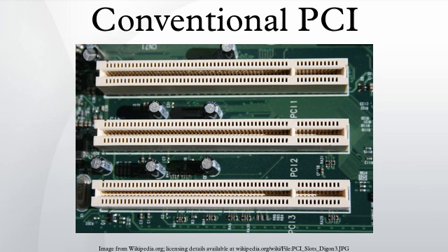If a memory space is marked as prefetchable, then the target device must ignore the byte select signals on a memory read and always return 32 valid bits. 0111, memory write, this operates similarly to a memory read. The byte select signals are more important in a write, as unselected bytes must not be written to memory. Generally, PCI writes are faster than PCI reads, because a device may buffer the incoming write data and release the bus faster. For a read, it must delay the data phase until the data has been fetched.